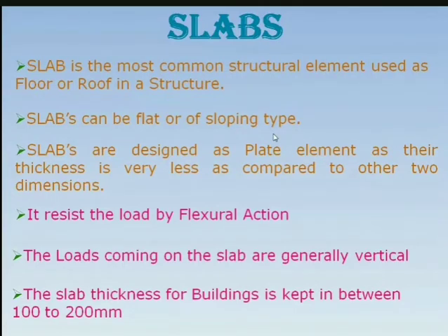Minimum that much we keep practically, but theoretically we can keep a thickness between 100 to 200 mm. So when you are designing, see that the depth of your slab doesn't go beyond 200 mm for a building. 200 also is quite big. Most of the times when we have practically designed slabs, even big slabs, they fit in 6 inches, which is 150 mm. So whenever you go on a site, first observe how much the slab thickness is. So this is what a slab is.